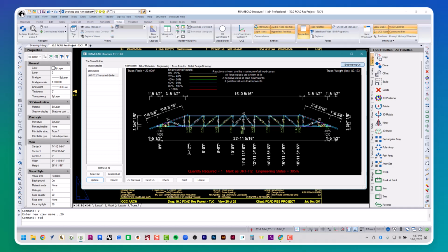When it comes to fixing a truss, there is no one correct way to do it. There are multiple ways to resolve a truss failure. We can adjust the truss material or adjust the web members and spacing. We're using an LE truss, which means the top and bottom chords are oriented flat. We also have the option of reinforcing our truss.